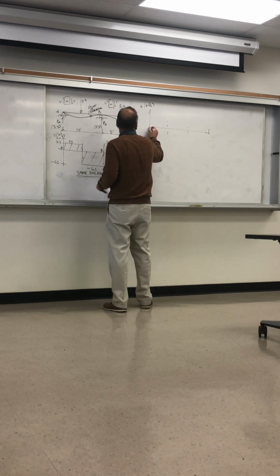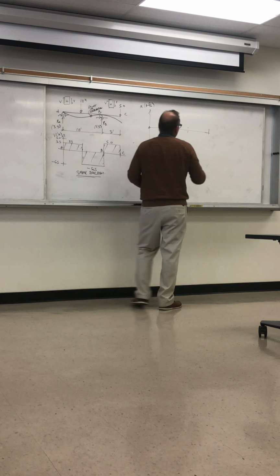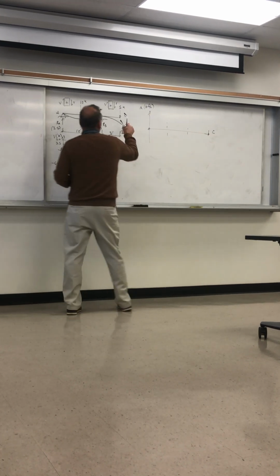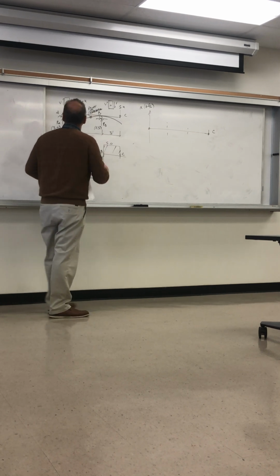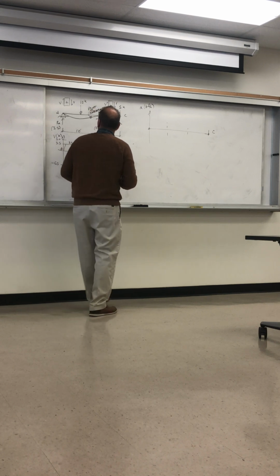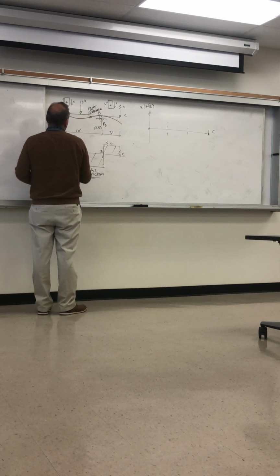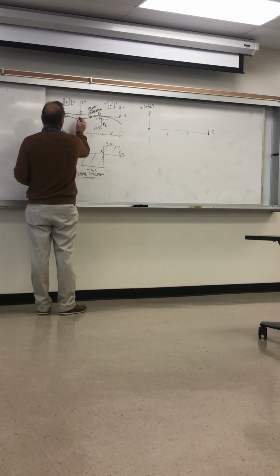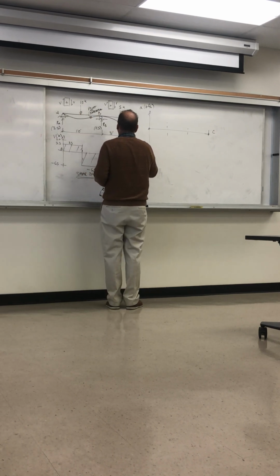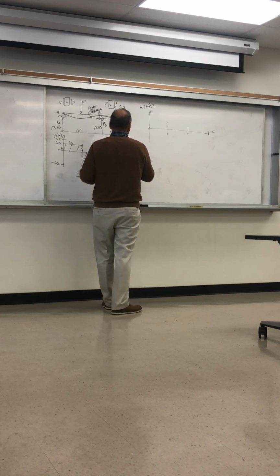So it's 0 here. It's 0 out here at C. This is where a vertical load is applied, so there's no moment there. No moment here, but there will be moment as we cross over here. The bending moment in this location here is this force times that distance, so that's 3.5 multiplied by 5. That's 17.5.